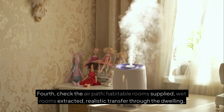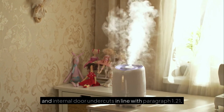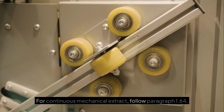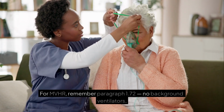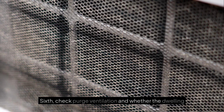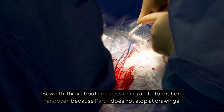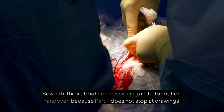Fourth, check the air path: habitable rooms supplied, wet rooms extracted, realistic transfer through the dwelling, and internal door undercuts in line with paragraph 1.21. Fifth, check the system-specific background ventilator logic. For continuous mechanical extract, follow paragraph 1.64. For MVHR, remember paragraph 1.72, no background ventilators. Sixth, check purge ventilation and whether the dwelling still has a sensible route for rapid ventilation when needed. Seventh, think about commissioning and information handover, because Part F does not stop at drawings.